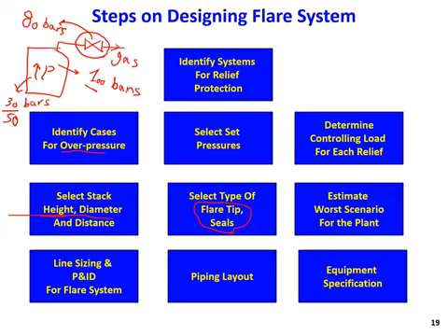As I said, we have to estimate the worst scenario, the maximum flow rate of gas that will be sent to the flare, and based on that we calculate all these specifications: the diameter, height, flare tip, seals, and so on.